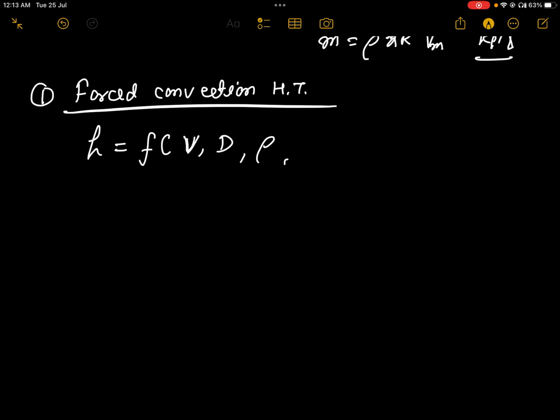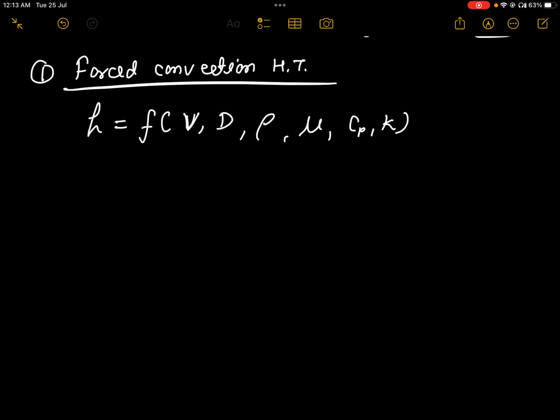Then it depends on the density, the dynamic viscosity mu, Cp and the conduction heat transfer coefficient K. These three terms, mu, Cp and K, are called thermophysical properties of fluid. This is very important.